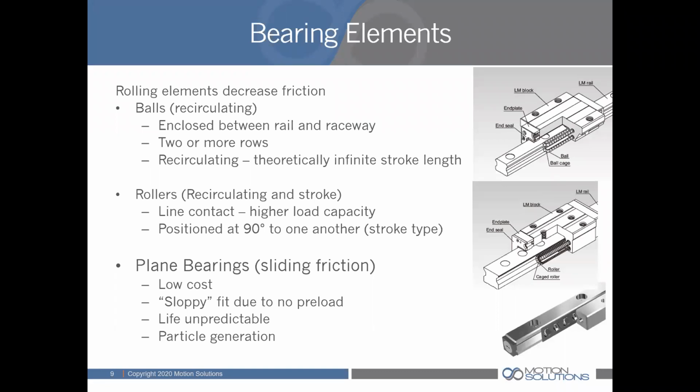And most ball rails are recirculating so that the balls enter and go out of the load zone of the carriage and return down along the block and re-enter the load zone. So basically, as long as your linear guide is, as long as the rail is, the block will continue to stroke.